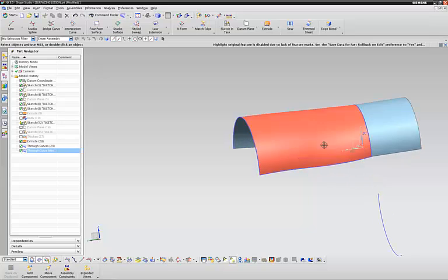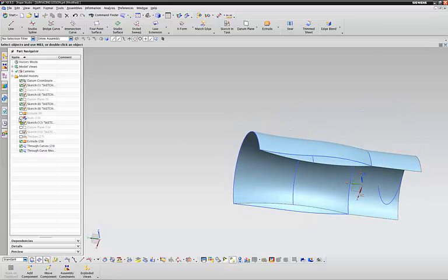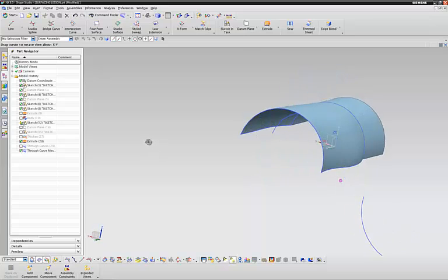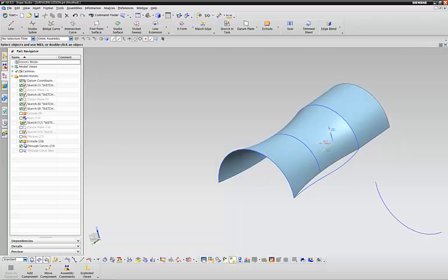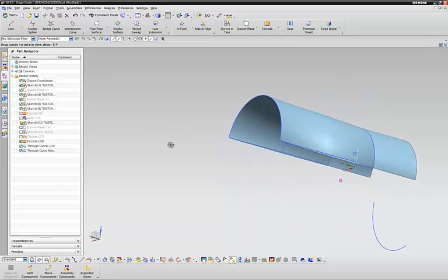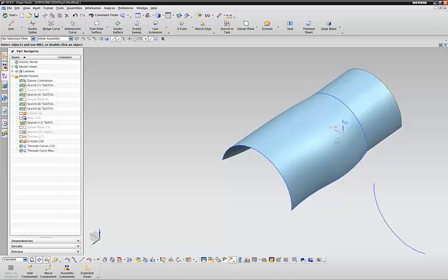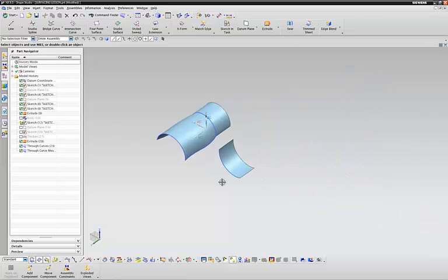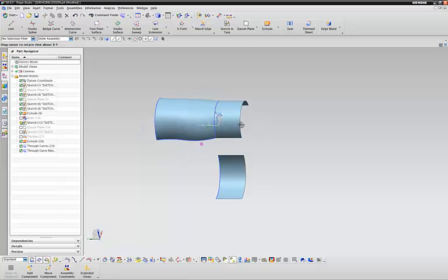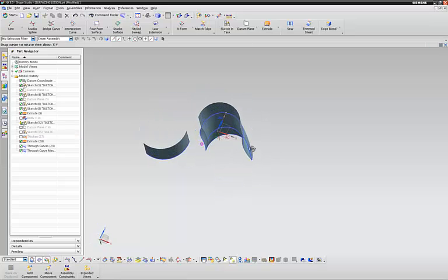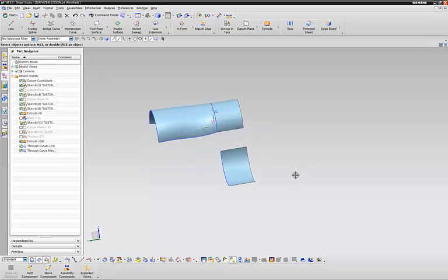You can turn them off by clicking the X next to their location, so you can look at either sketch if you want. Just the outer one or the inner one, depending on your preference and the needs of the part you're making. You can see over here you can extrude this line, and you can see they're lined up next to each other mostly. Just extrude it like I showed before.